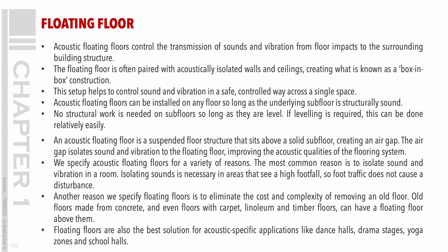Acoustic floating floors can be installed on any floor so long as the underlying subfloor is structurally sound. No structural work is needed on subfloors so long as they are level. If leveling is required, this can be done relatively easily. An acoustic floating floor is a suspended floor structure that sits above a solid subfloor, creating an air gap. The air gap isolates sound and vibration to the floating floor, improving the acoustic qualities of the flooring system.